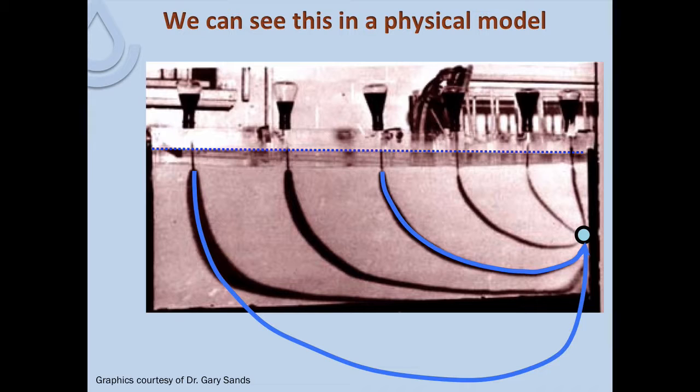It's just more difficult for that water to be able to flow into the drains. And especially if we put them in the restrictive layer or below the restrictive layer, now we limit the ability of that water to get to the drains.